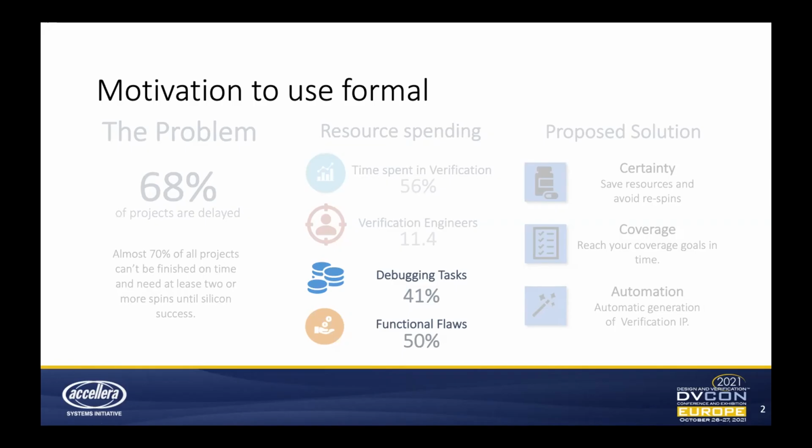Just imagine we were back 20 years and you would need to do all the verification that we have today on the gate level, because you couldn't trust the RTL for your design sign-off. We somewhat have the same situation today. We need to do all the verification on the RTL because we don't have an abstract model that we can use to do functional verification.